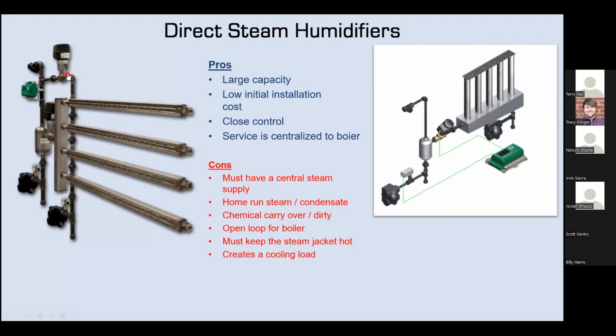So this top control valve supplies pressurized steam into a jacket that surrounds these tubes. And what that does is make sure everything's very hot. And so when you get that jacket up to over 212 degrees Fahrenheit, that's when you're allowed to open up the steam control valve for the space. And then it comes out of these nozzles without any condensate. You don't generate any condensate in the distribution, and you get really good short absorption distance with these jacketed systems.